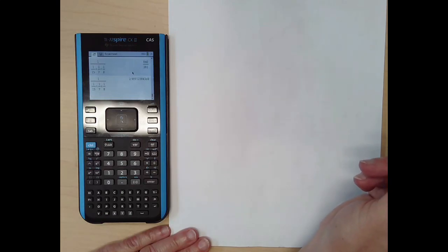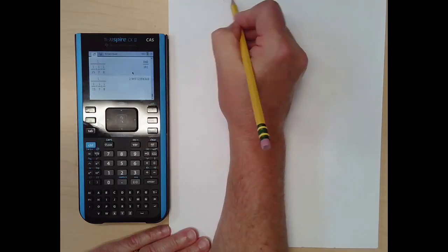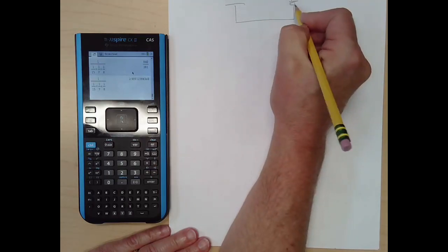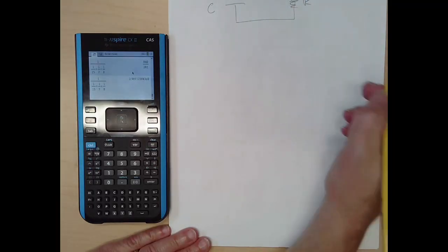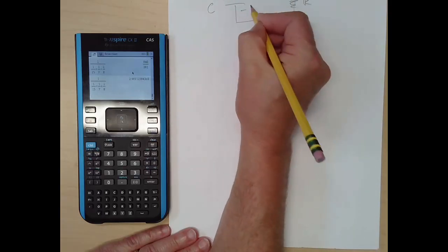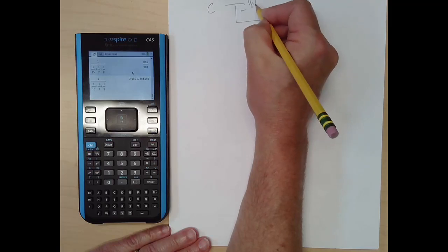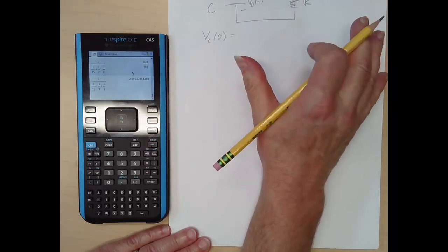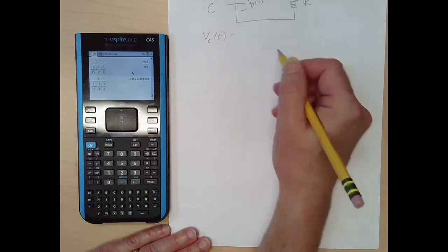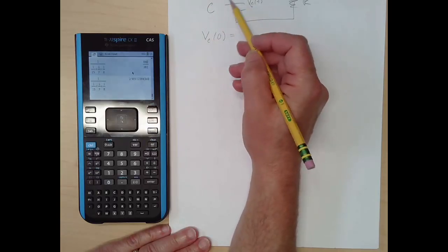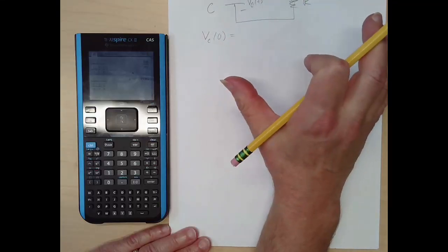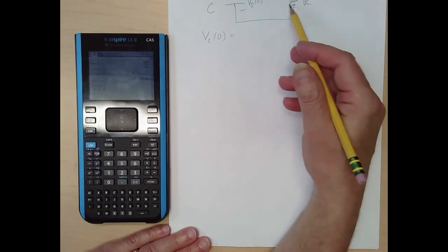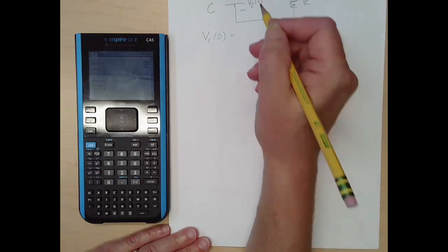I'll call this number 2. Let's put a switch in here that can be closed at some time. What if we have a circuit that has a resistor and a capacitor in it? At some time t equals 0, we're going to close the switch, and we'll assume that V sub C at 0 is not 0, so we have a charged capacitor. When we close the switch, the capacitor will discharge through the resistor, because capacitors and inductors store energy. If the switch is not closed, no current flows and the capacitor holds its charge. But when we close it, the resistor, a lossy element, dissipates the energy until the circuit's energy goes to 0.